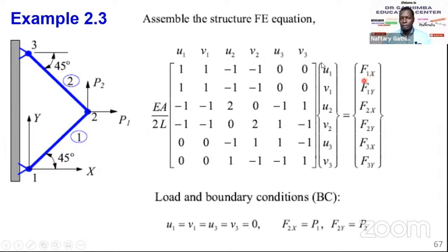So all you need to do is substitute those values in this equation. And again, you condense. You remember the way we said, where you have the values of U's as zeros, you can remove those rows and columns so that you can have a condensed equation, row reduction. Because again, with a 6x6 matrix, if you try to think of Cramer's rule and getting the inverse of such a matrix, I don't think you can finish by manual calculation today, unless you work it on a board. It is quite a tedious task. So use the row reduction method or Gauss elimination method.